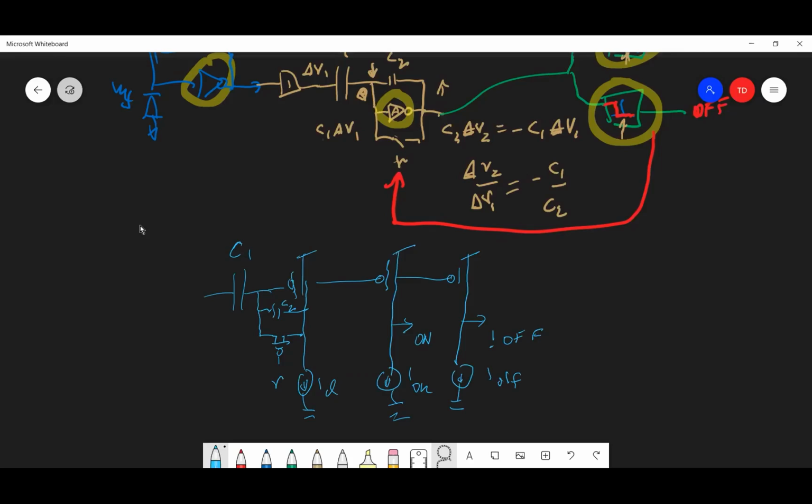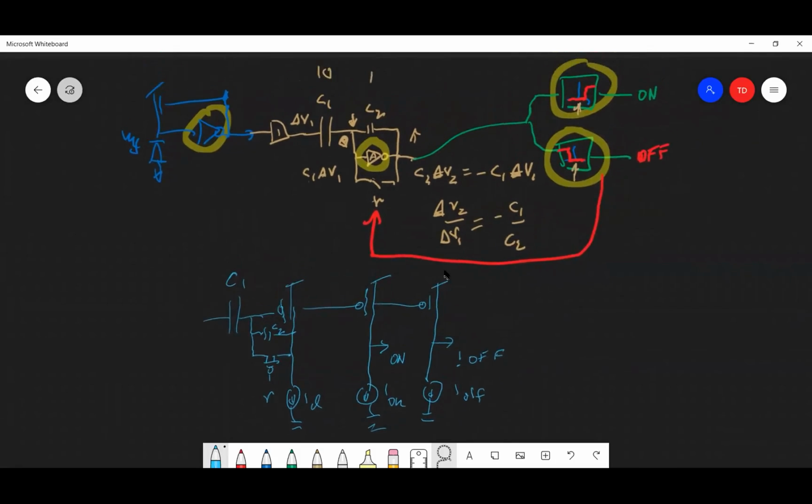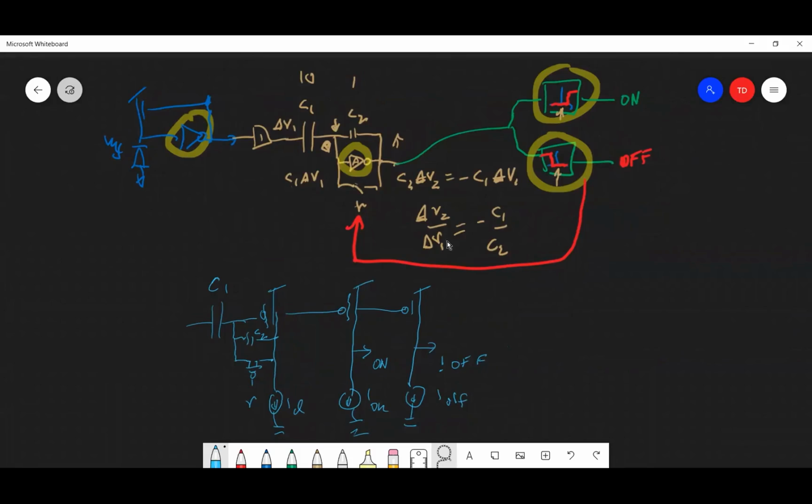That's the complete circuit. 7 transistors, 6 big transistors because you want them to match well, because you want to have a decently matched threshold, and then 1 reset transistor. Hope that you guys can look at that later. See, that's really the same circuit. Nice and simple, huh? All kind of beautiful properties about this.